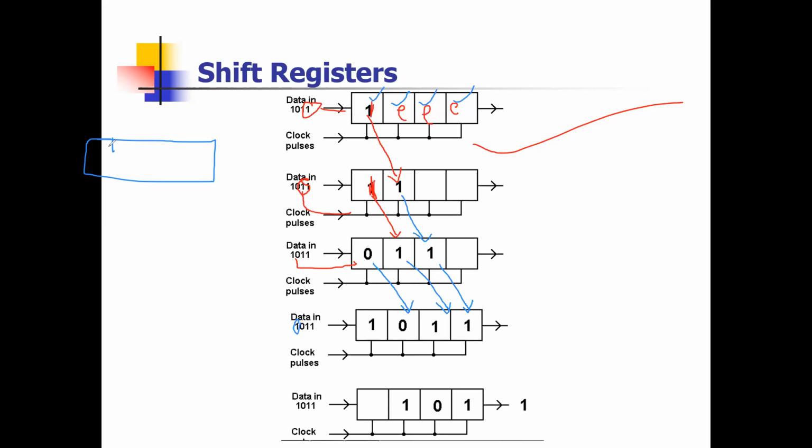Hello? Yes, Miss. Okay. So how will you know that there are 4 flip-flops? Because here are 4 boxes. Can you see? I didn't draw the complete flip-flop. And you know, whatever data you are giving, you are saving the same data. That means we are talking about a D flip-flop. In the circuit which I showed you, all are D flip-flops, because only for the D flip-flop, whatever data we give, we get the same. So this shift register has D flip-flops, as we studied before.